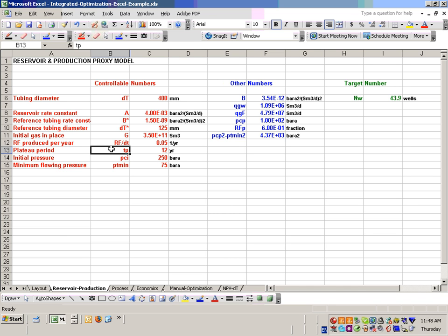And here we've got basically one sheet. This is our surrogate for the reservoir simulator. And I can guarantee you that it's going to give you essentially the same answer if you take the time to put in the tubing tables and so on. If the permeability is above about 1 millidarcy or even probably 0.1 millidarcy, this will give you the same result as your 100,000 grid cell gas reservoir model. So you may not believe that, but you can confirm that to yourself. That's up to you to do. I've done it before.